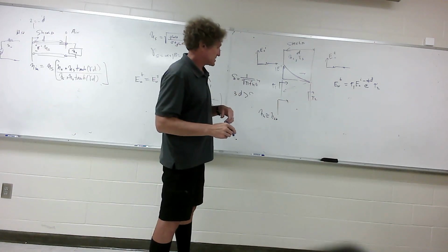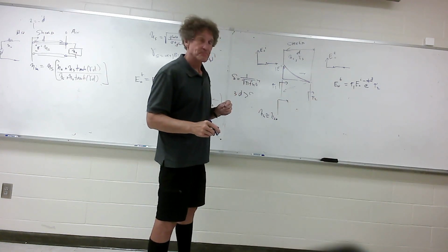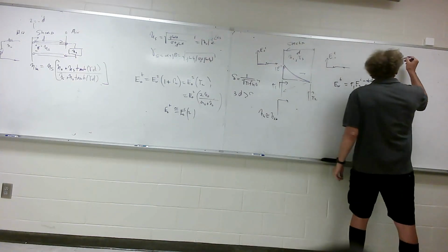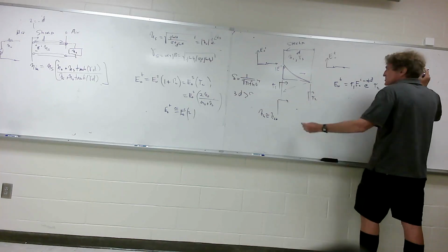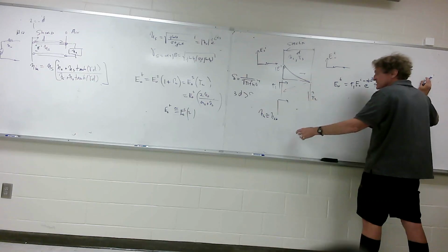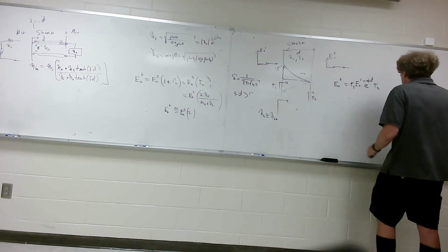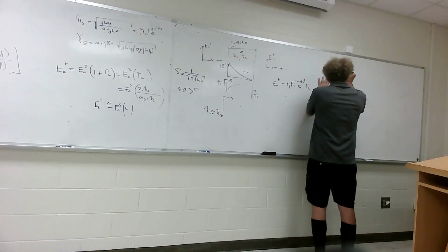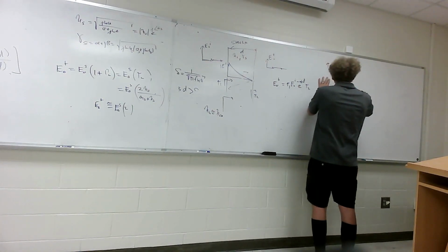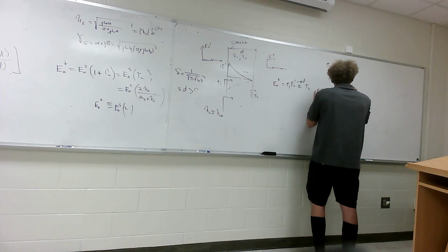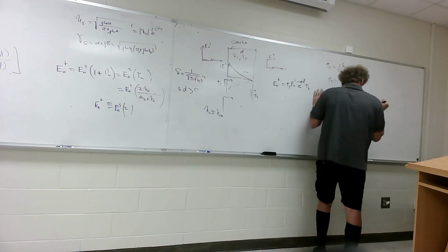I'm going to write down what tau 1 is and tau 2. First, for tau 1 here, tau 1 is always twice the impedance you're going into. Since this is assumed to be a thick shield with many skin depths, the input impedance is about eta shield, so it's going to be 2 times eta shield over eta shield plus eta naught. And tau 2 is going to be equal to 2 times eta naught over eta naught plus eta shield.